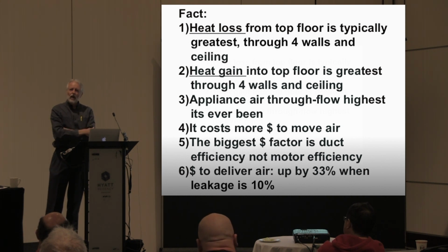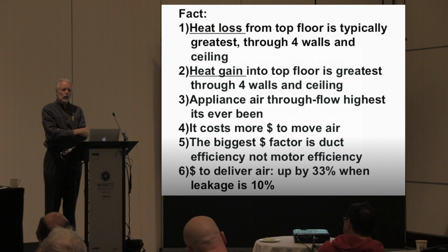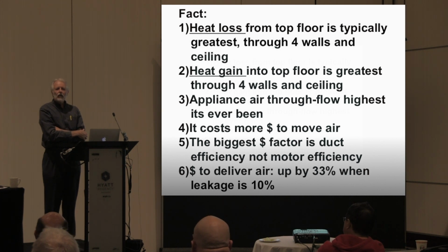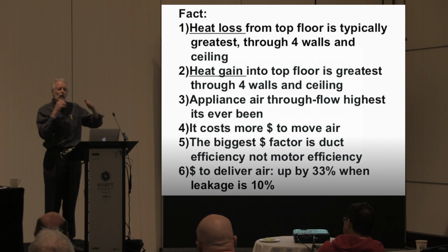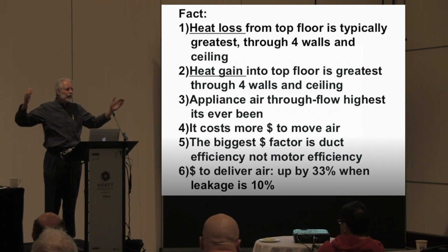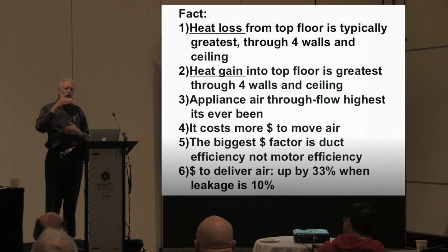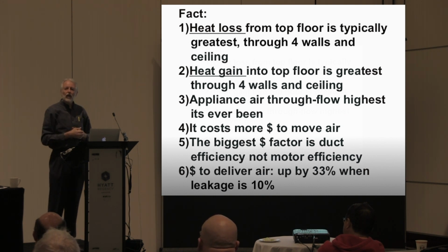It costs money to move air, but what I am going to show you is that the cost of moving air is in part because we're strangling the ductwork systems and causing ourselves to use the 3/4 horsepower motor he's suggesting. In ignorance, we don't realize that the cost of moving air is only partly dictated by how much efficiency you bought in the motor. The biggest part of your electrical cost of moving air is the ductwork, which you're asking that fan to push the air through.